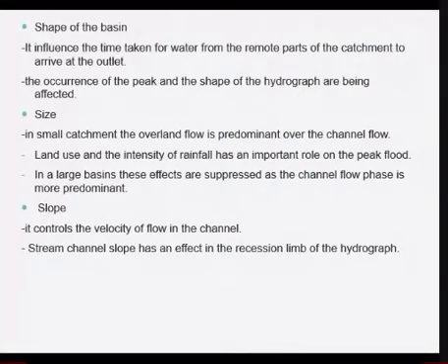Shape of the basin. It influences the time taken for water from the remote parts of the catchment to arrive at the outlet. The occurrence of the peak and the shape of the hydrograph are affected.